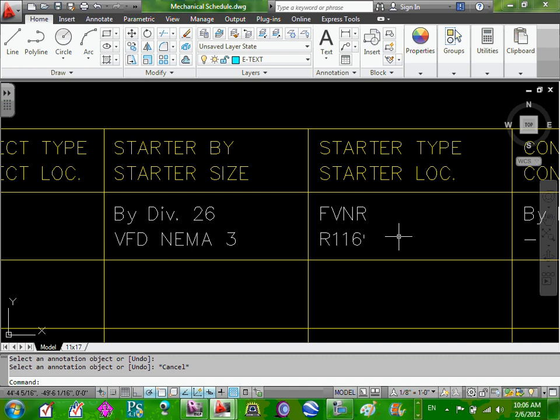What is a full voltage reversible? It doesn't do speed control or ramp the motor up and down. All it does is start and stop the motor, but this time in two directions. That's also another cheap piece of equipment, except one step ahead, right? Because it allows you to reverse the motor. All these are control methods.